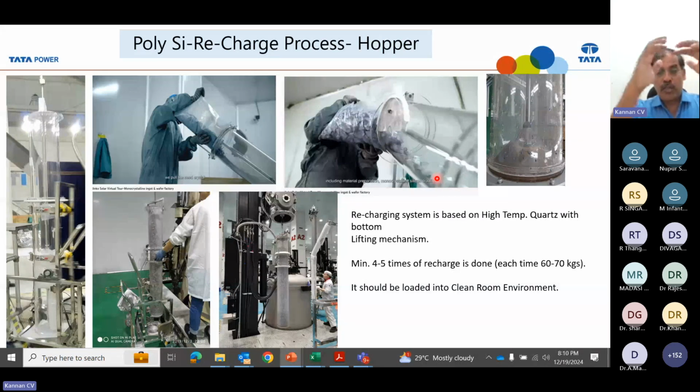So even after growing the crystal, without shutting down the furnace, you can load the charge again and grow one more crystal. Instead of one crucible for one crystal, as it was 5 or 6 years before, now industry is doing 5 to 6 crystals at a time. Earlier, one crucible handled 400 kg one time; now you can use 2000 kg of material using one crucible. So you can minimize the overall downtime of the machine, grow more ingots in a shorter period of time, and the crucible life is also extended.